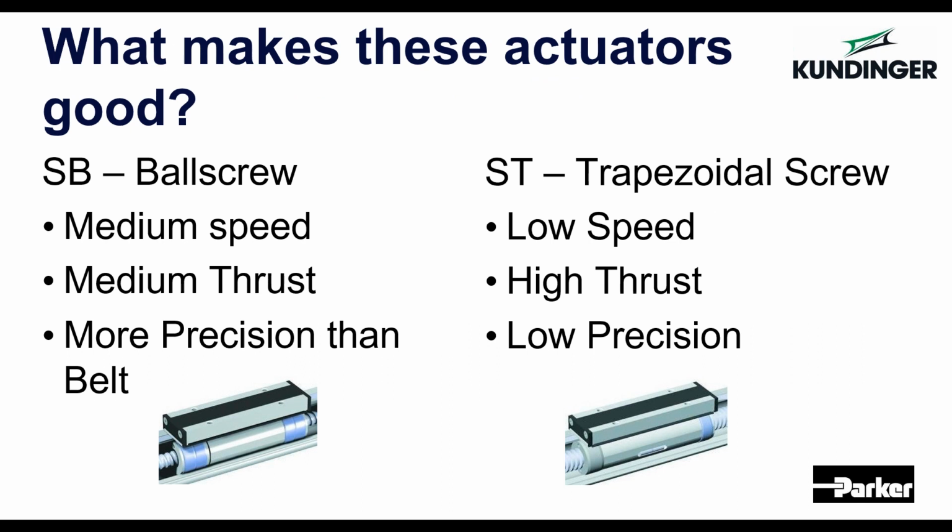That being said, there is an inherent disadvantage to belt-driven and ball screw products in vertical, being that they are such high efficiency that they are back drivable, meaning in a power down situation where the motor loses all of its holding torque, the payload does have the potential to drop based on the lead of the drivetrain and what kind of inertia there might be in the system due to gearboxes. In the days of modern servos, this is easily combated with fail-safe type holding brakes, but that does add some cost. In a lot of these OSPE type situations, these are very cost-sensitive applications.